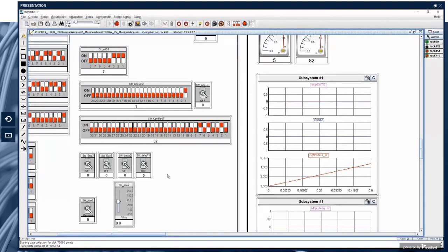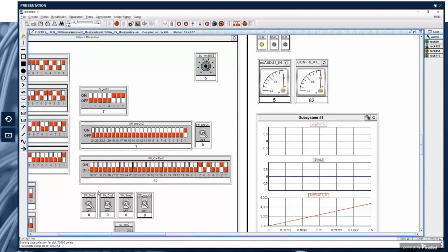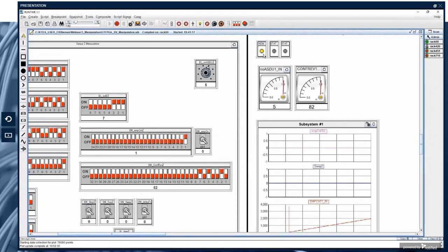Next, we can focus on stream manipulation. Currently, the stream manipulation mode is set to 0, which is stop and resume. We can apply stop manipulation by toggling this switch. You notice that the new packet indicator is gone, and the subscription status is lit up. That means the SV stream is lost. We can change it back by toggling this switch again. Now you can see the subscription is successful again. The error ID is turned off.